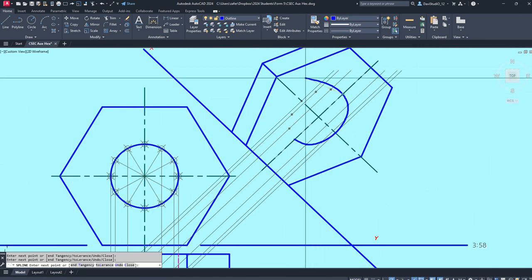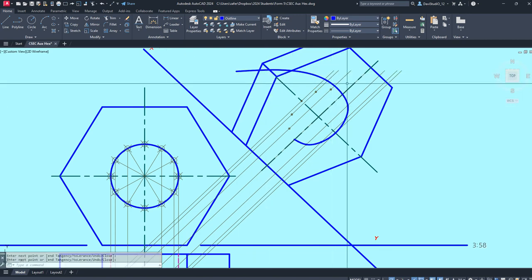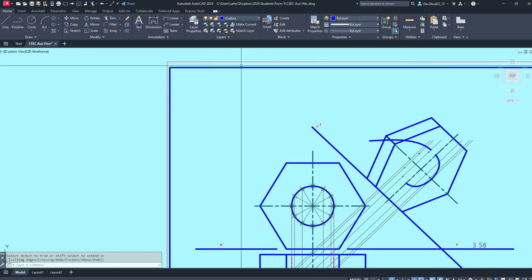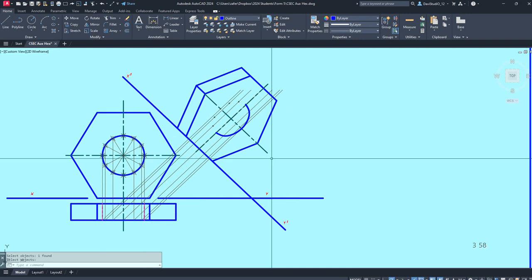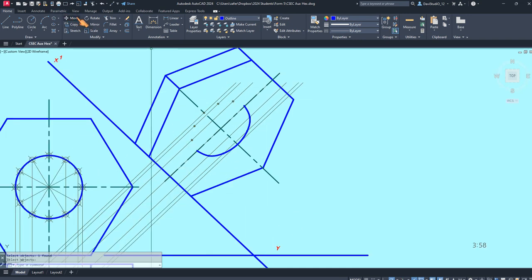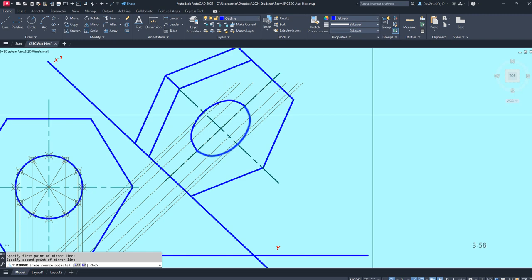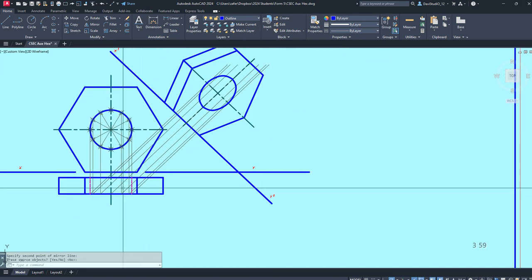Now to ensure that we have the top smooth, you could carry the point a little further out. Enter, and now you just trim that and erase the rest. The reason why I did it in two pieces is because the problem asks for hidden detail. Now to complete the whole, we can mirror this here to be the hole there. Enter.